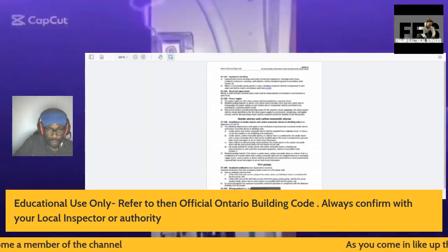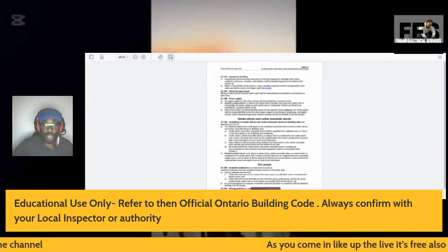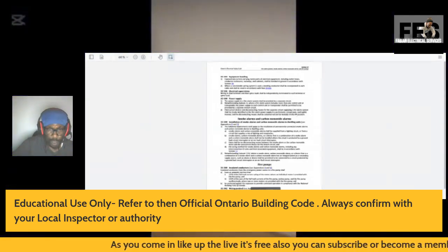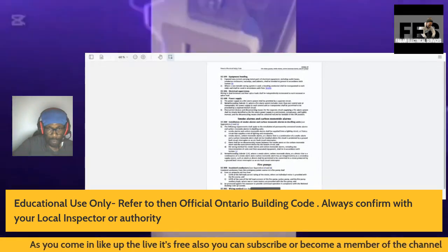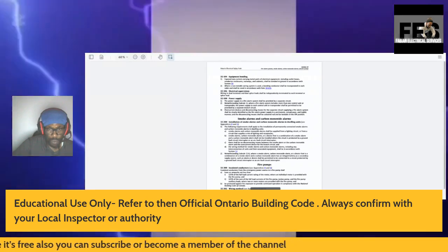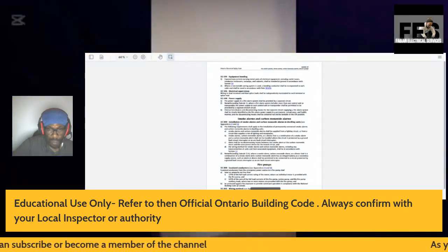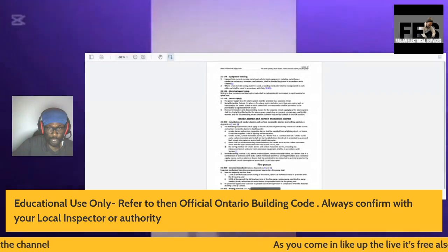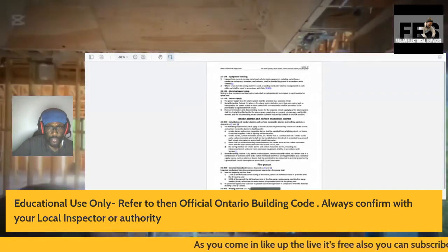You're going to see that I do supply the smoke alarms with a lighting circuit. That's how we do it in Canada. We provide the power through the use of the lighting circuit, and it has to be straight power, no switch to turn off the smoke alarm.